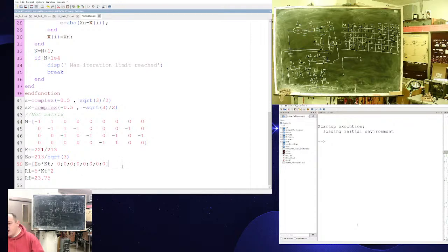I have only one source here. In real life, if you have a distribution network with radial power, the situation will be the same, only one source. If you have a bridge between two substations, a bridge line, you will have two of them, one on each side of the bridge. And both should be multiplied by the reduction factor.